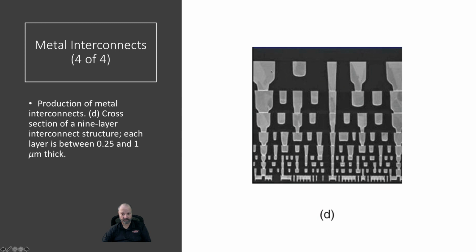That's metal lead that's cross-sectioned. So this is probably around 1/2 micron, the via. So the 1/2 micron via hole has got to be aligned, you know, to the level 8, okay, which is slightly smaller than the level 9 lead.